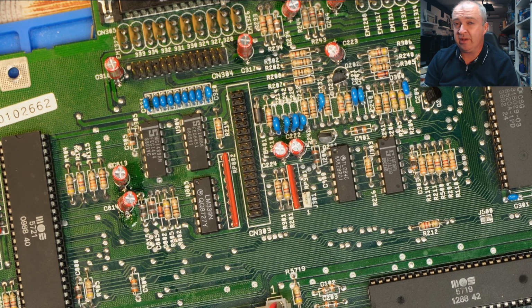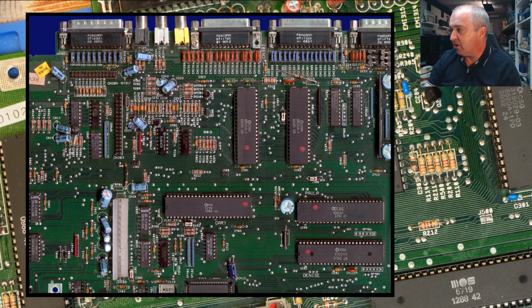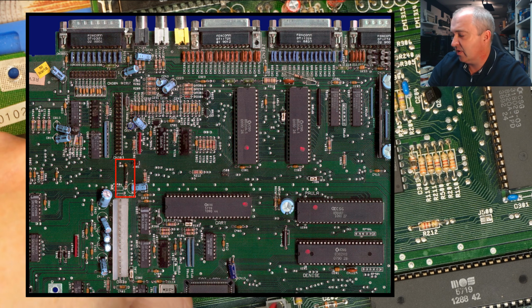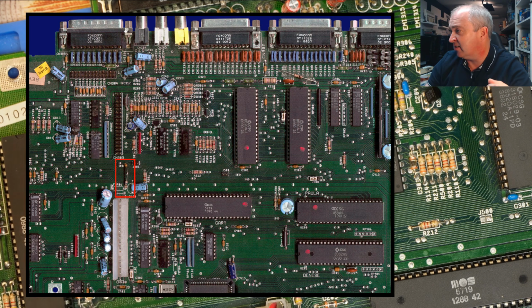Right, want to go back to that photo of a full 6.2 board that we found over on the Amiga hardware database. Because if we take a look at it, we can actually see that modification on a 6.2. There it is. There's a capacitor with a resistor below it, tied to ground. And yeah, right enough, there is 4 solder vias at that point on a 6.2 board. So it is definitely the most right-hand via looking at it on that image.